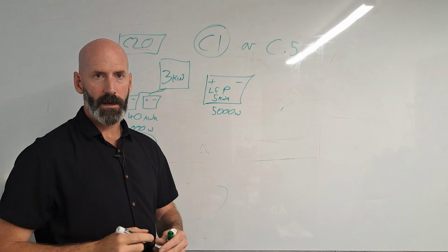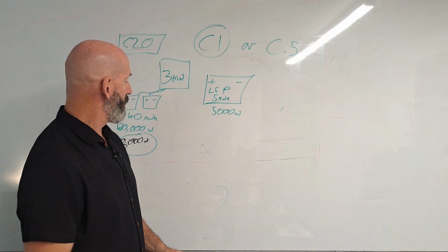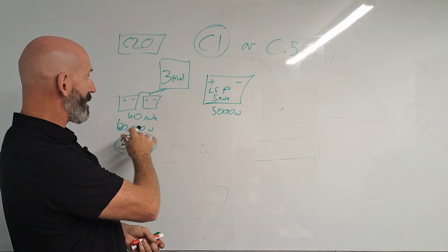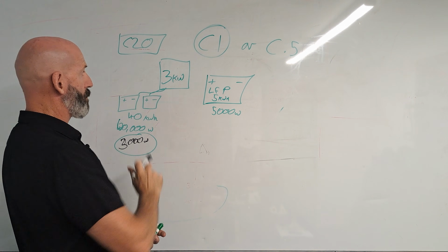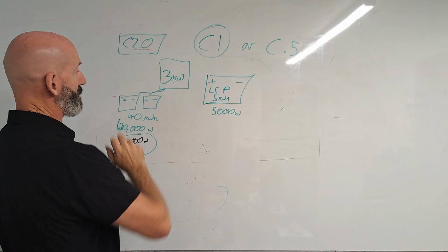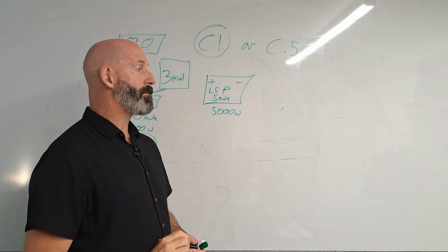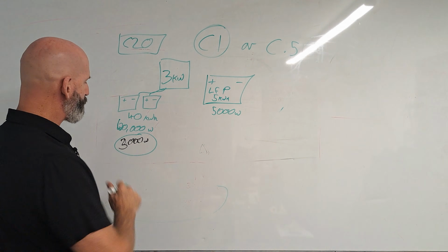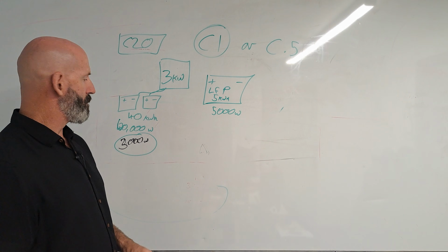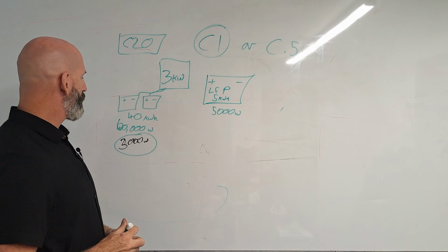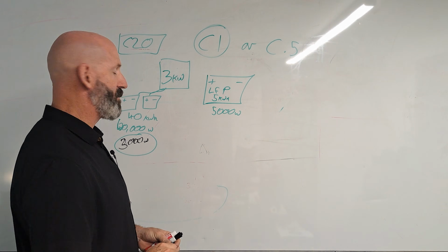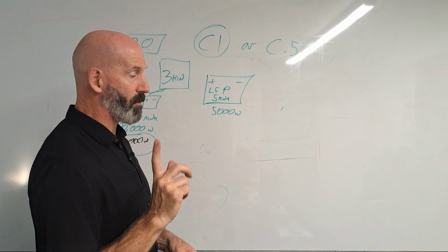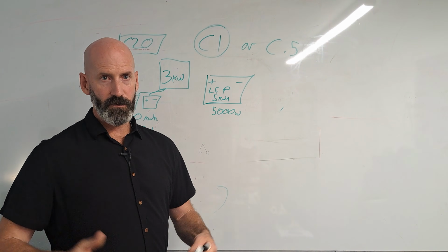So one 5 kilowatt hour lithium battery can give you 5,000 watts. You've got to build a 60,000 watt or 60 kilowatt hour battery bank to be able to provide a 3 kilowatt inverter if it has a C20 rating. Most of your cheap batteries have a C100 rating. So when you take 60,000 watts divided by 100, you get 600 watts is your maximum output that you can take off that big battery bank. You'll find that on your cheap batteries, so watch out. This is why we use lithiums.